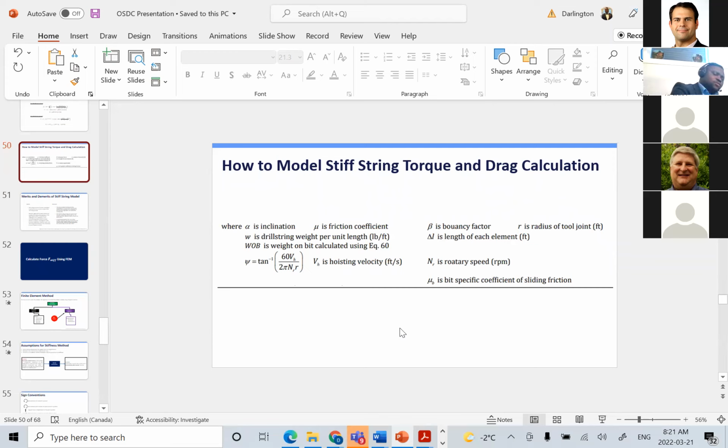Well, at the end of the day, there's a force acting in the axial direction, right? And that drilling mud is part of the force. So the drilling mud density and everything that affects the drilling mud is part of that force acting in the axial direction. So that can even become a load in the drill string. If viscosity affects the drilling mud, and the drilling mud is part of the forces acting on the drill string, then yes, it has an impact.